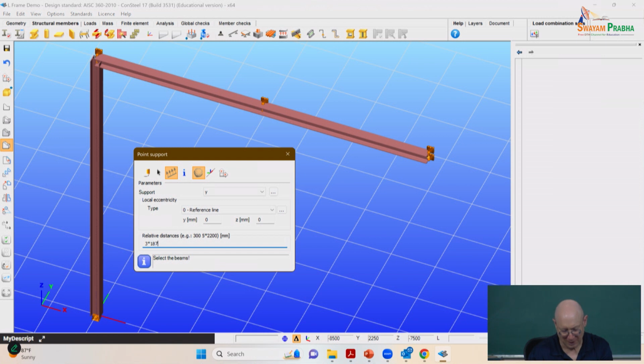Oh, out of plane. Okay. Yeah, we've been talking about an in-plane analysis, and now I'm jumping to it being a structure, so we have to actually support it out of plane, right? We did a planar analysis, but we can look at the out of plane buckling here in a bit. But then you need to know how many out of plane braces you need to provide.